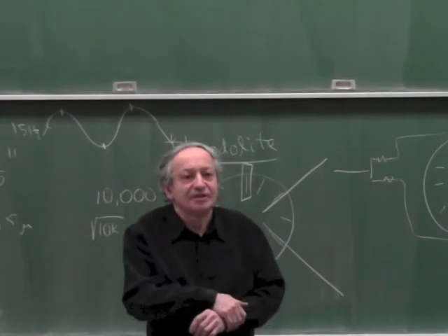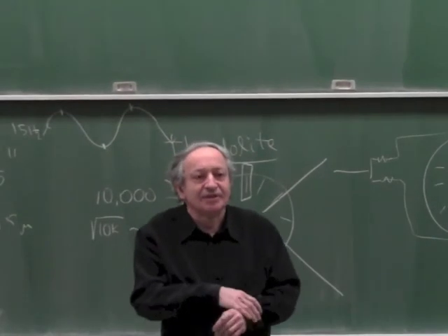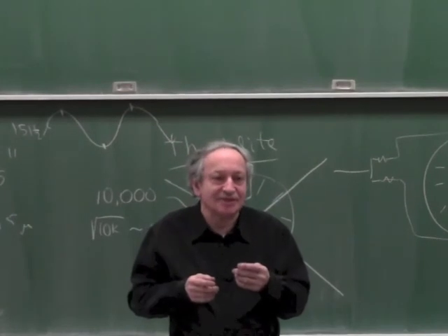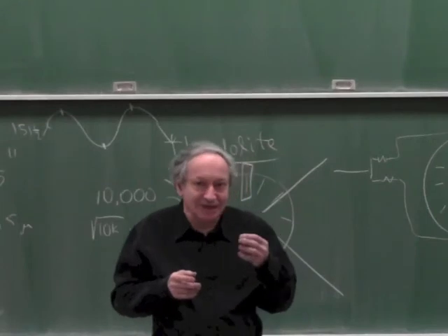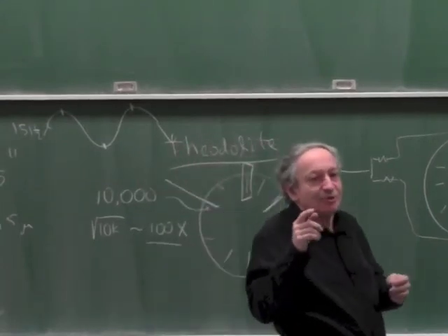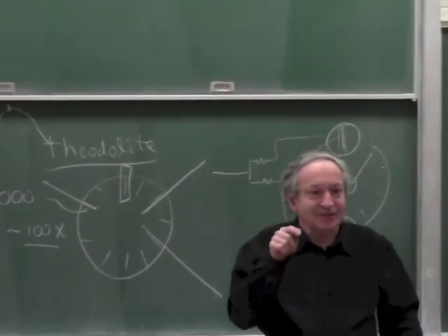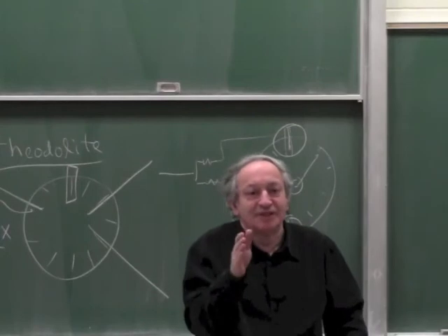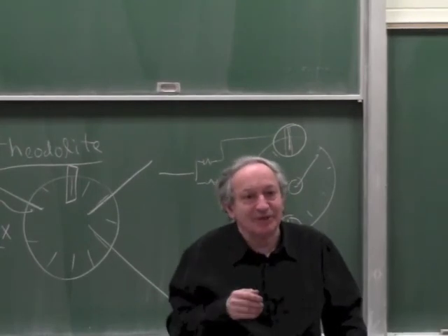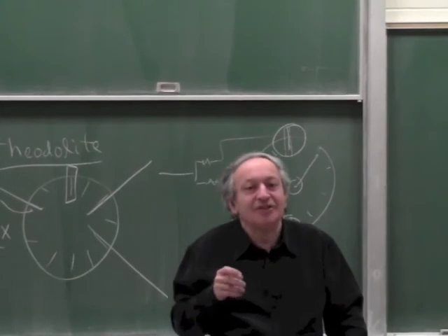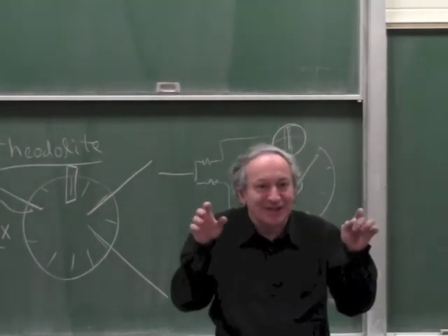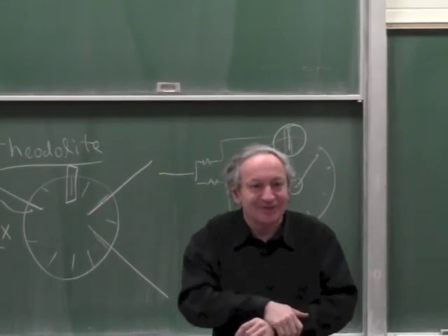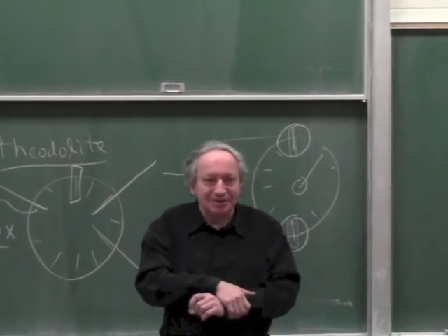Yes, please. Could you use multiple cameras to phase shift it to capture? Yes, but then they have to be registered to one another. You can always do some parallel shifting because you can control the sample point in a camera by the trigger. So you can have 10 cameras, each one at 15 Hertz bandwidth, but each one shifted a tenth of a cycle. Then you will get 10 times the bandwidth, but it's still only 150 Hertz. And you have to register the 10 cameras so the images align. Otherwise, when you jump from camera to camera, it appears the object is jumping. So it's problematic. It can be done, but it's not worth it.